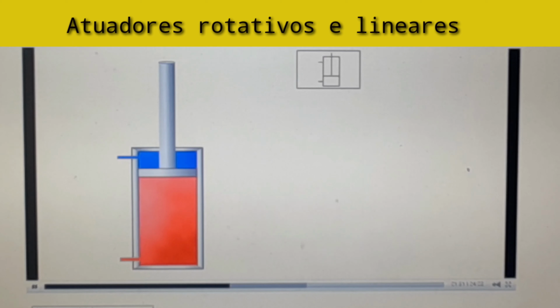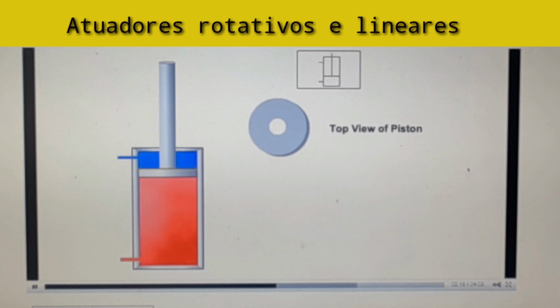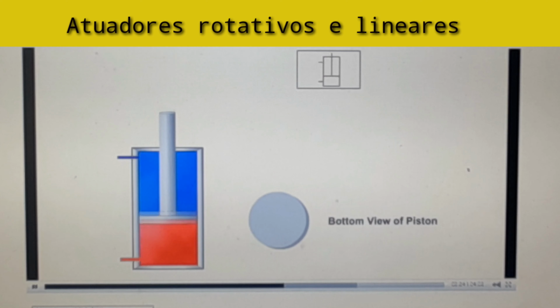A double-acting actuator transfers linear force and motion in both directions. It is operated by hydraulic fluid that is pumped into one of the two cylinder chambers. The fluid forces the piston to move. With a constant pump flow, the speed and force at which the cylinder rod extends and retracts is not the same. Can you guess why? Well, the cylinder rod takes up space inside the cylinder, so the amount of fluid required to move the rod is less. Also, the piston surface area on the rod side is smaller. This means the cylinder will retract much faster but will have less force.